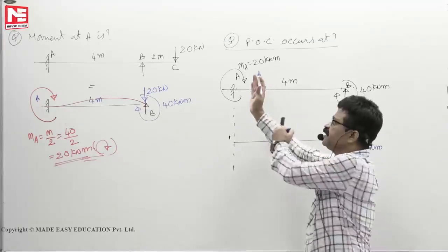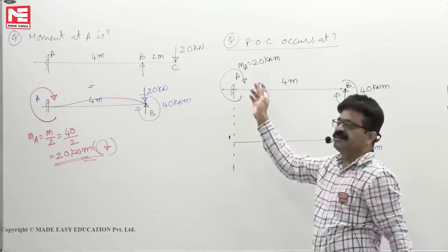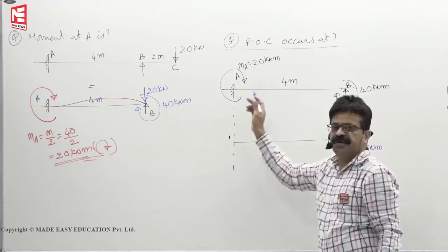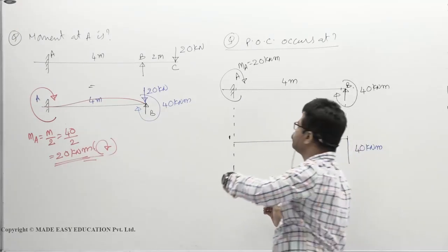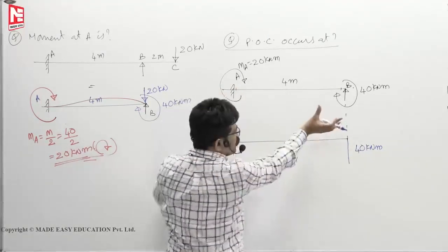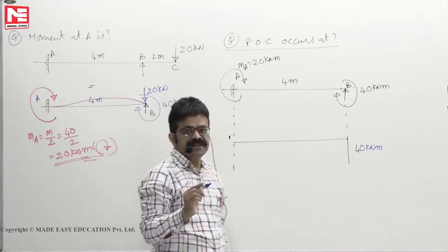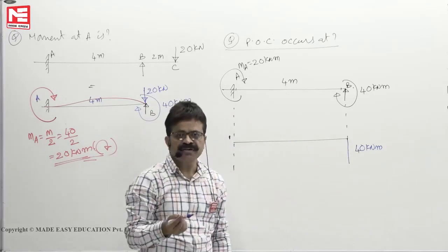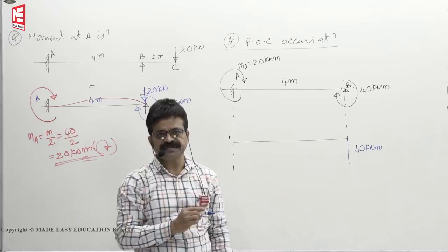Why headache? Stand here, look left side. Only moment. So, section left side clockwise, it will sag the beam. So, it will sag, it will hog. So, the same clockwise moment can sag the beam or hog the beam depending on its location.